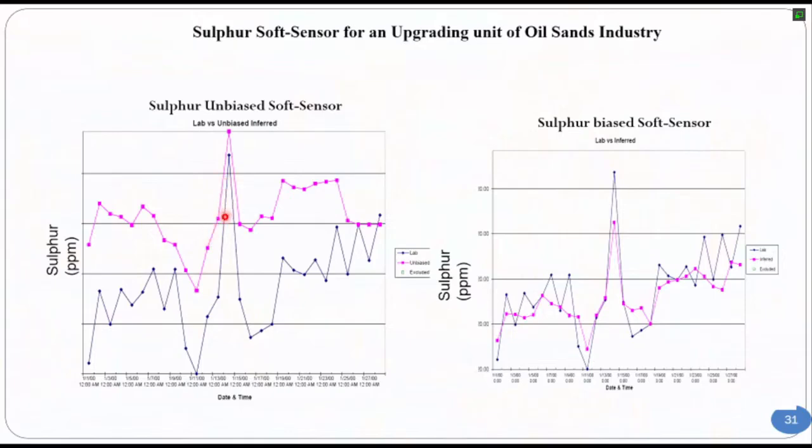Let's suppose it is very close here and it is going in a negative direction. It indicates that there are lesser amounts of ppm, but actually the process is emitting higher ppm levels. The direction of the variable is critical for me. So in the first case, I'm only looking at the direction part. Once this direction is fixed, I'm correcting the model. I'm just adding the error and matching the model.